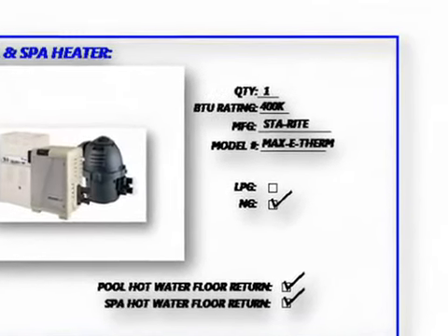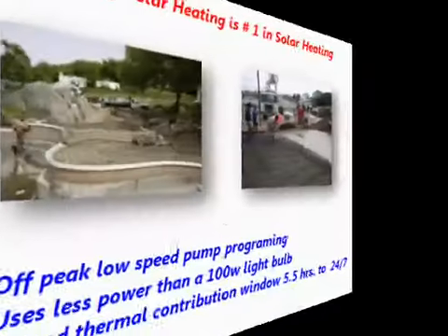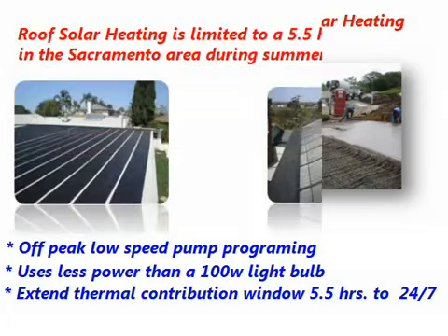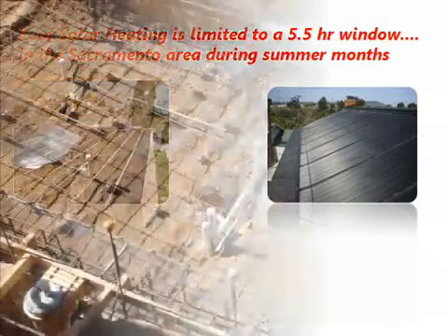There are several ways to heat a pool or spa, but in any case you can improve the ability to heat a pool by as much as 67% by simply delivering the heated water to the bottom of the pool or spa instead of using the surface returns. The thermodynamics between the pool's heated water being delivered to the bottom of the pool and being blanketed by the surface's cooler water reduces the heat loss experienced through the surface evaporation while heating.